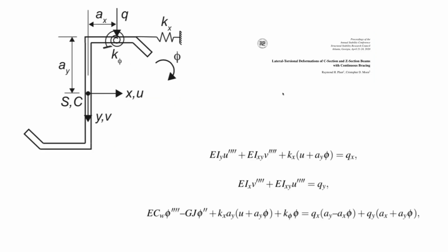Now I'll take it one little step deeper. I would say the core piece of this analysis in this example is doing a second order structural analysis of the purlin line. And how do we do that? We have some tools to help approximate that. Some of you have worked with Mastan 2, which is an excellent program, used both in the educational world and in academics for teaching. We all use it for teaching. It can also be used in design.